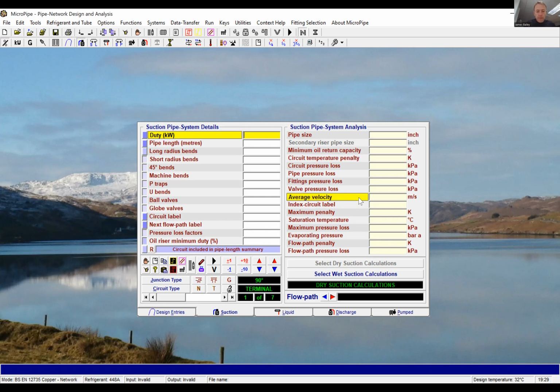So we've got 9 kilowatts, just 1 meter. I'm going to allow some bends for some losses from the coil within the evaporator. Standard amount, I'm going to stick in 6 bends. I've shown a high level isolation valve. Some coolers come dressed with valves, so no problem there. I'm going to stick a valve in there. It's the first circuit, and it flows into the second circuit, which is its riser to take it out of its box to high level above the cold room.